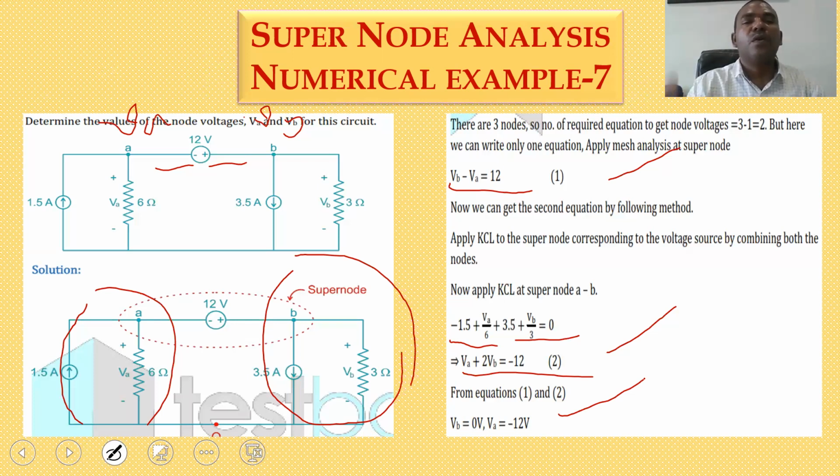So like this, you have to go for super nodal analysis or nodal analysis for any electrical circuit. Remember, students, any electrical circuit can be calculated using Kirchhoff's current law, that is nodal analysis, Kirchhoff's voltage law, that is mesh analysis, any network theorems, network reduction techniques, or network topologies. Finally, you have to get the unique value only.